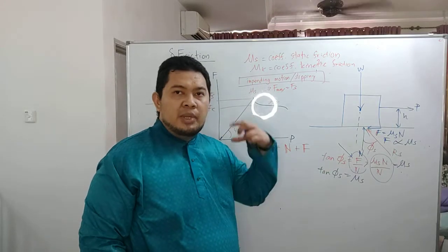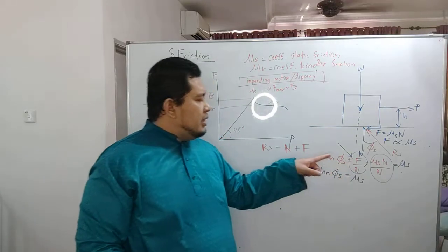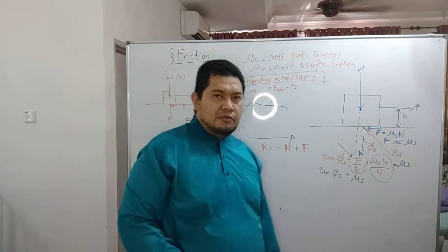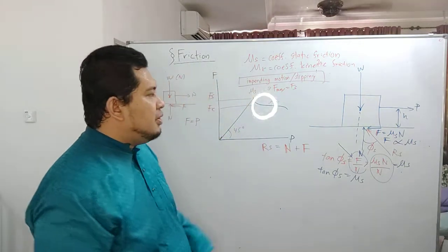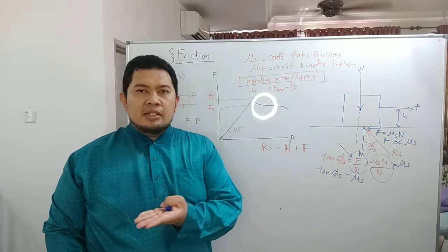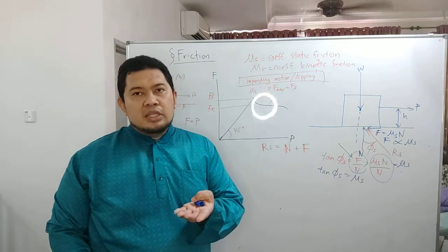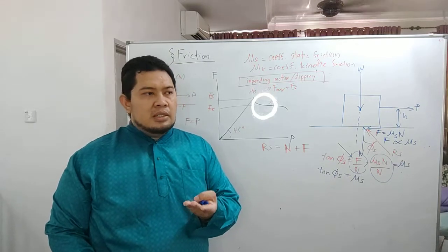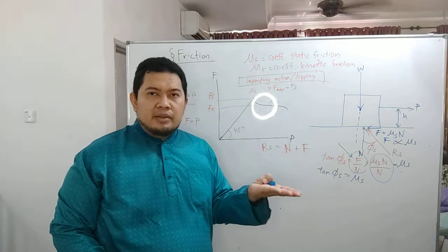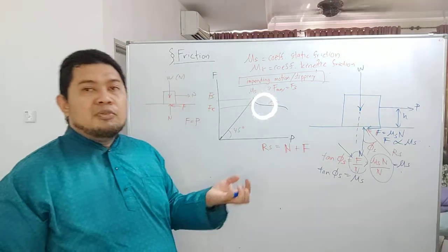If you have a bigger friction force, you can have a bigger value of the coefficient of static friction. Say for example, if you compare a rubber surface and a tile surface, the tile surface usually has about 0.3 as the coefficient of static friction, but on a rubber mat or rubber surface, you can exceed that, going above 1.